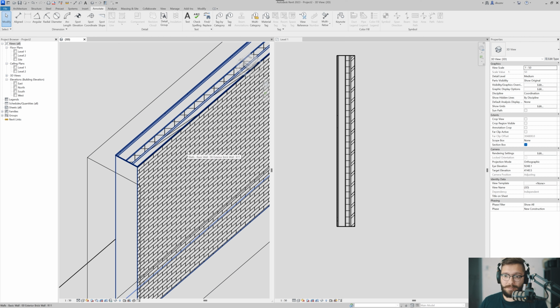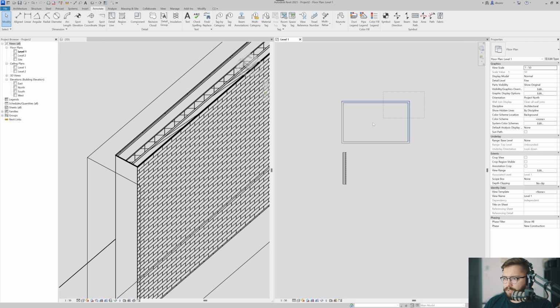So this is the next step. We've created the wall. It works. It's great. Now I need to model it in 3D space. And I need to model in such a way that if I ever need to change something about that wall, it's not going to mess up my project, okay? And which makes just more work to do. So I would delete this, all right? And I would create 4 grid lines.